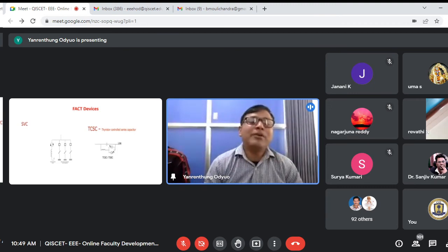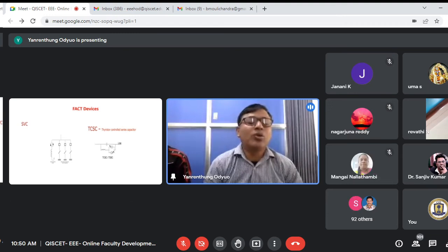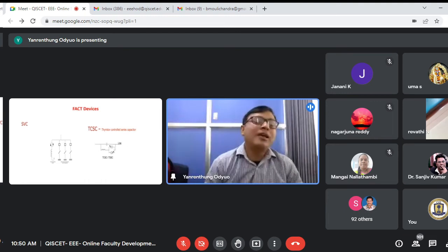Similarly, this is for capacitor as well as for reactive injection also. Suppose in a lightly loaded condition the voltage is more, then they have to check how much voltage is increasing. Based on that, how much reactive var they need to inject, and based on that, what firing angle they have to choose. That lookup table is also there. So from that only they are utilizing that firing angle, and they are injecting that var.